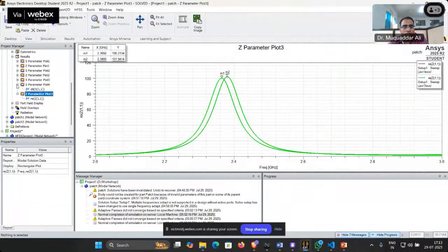Okay, so by this, we can say that our antenna is resonating around somewhere here. Why are we not exact? Because in the traveling we are doing along the line, we still have some gap between the ground and the microstrip that we have to account for. So overall, we can have a decent antenna here, and we can identify the proper matching. So whenever you are identifying the resonance mode of your antenna, you should be using de-embedding.